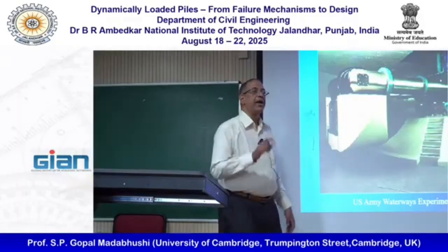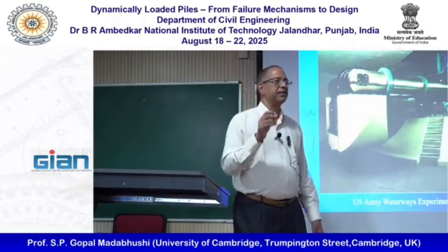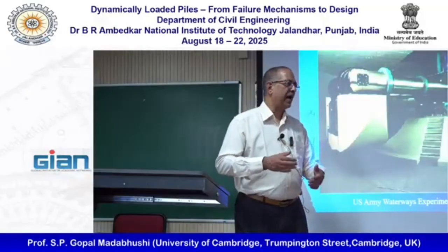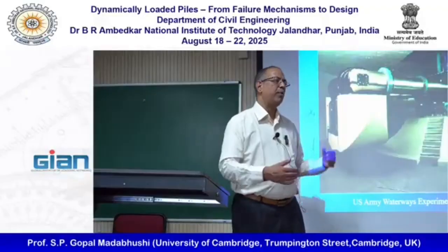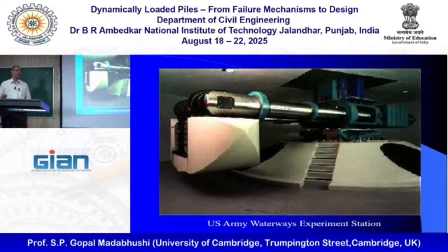And again, this is a 700 G ton machine. Most of the centrifuges are classified as G tons: how many tons of soil it can carry and what is the G it can go up to. Our centrifuge can carry 1 ton in Cambridge and can go up to 150 Gs. So that is a 150 G ton machine. This one is a 700 G ton machine, so it can carry a soil of 2 tons to 350 G. The Bombay one is a 200 G ton machine, if my memory serves right, about 3/4 of a ton up to 200 G.